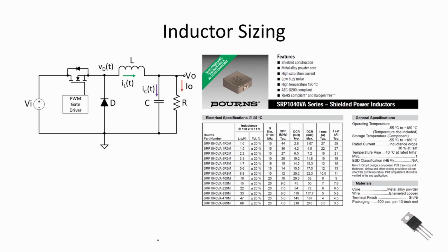Using a search engine such as found in either DigiKey or Mouser, I did a quick look for an inductor in the 22 microhenry range, and we see right here we have one that's 22 microhenries, and it was a Bourns. I have to also look at the current. That's the other spec we need to look at, and the rating on this device was 6 amps RMS for the current. And because we are at nearly DC, 6 amps RMS will also exceed our current requirement of 2 amps at DC.